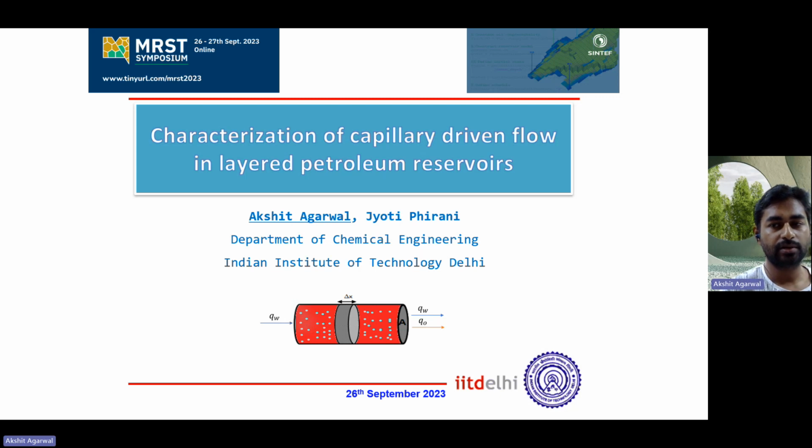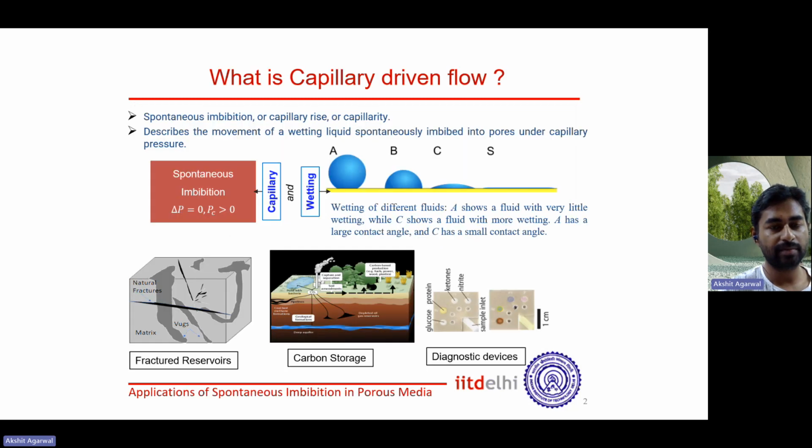Now today I am going to talk about the capillary driven flow in layered petroleum reservoirs, and this work is a part of my PhD thesis. So the first question which comes to our mind is, what is the capillary driven flow? It means that the wetting fluid will imbibe into a porous medium to displace the non-wetting fluid without any external interference. That is, delta P is equal to 0 and PC is greater than 0. Means that free spontaneous imbibition occurs.